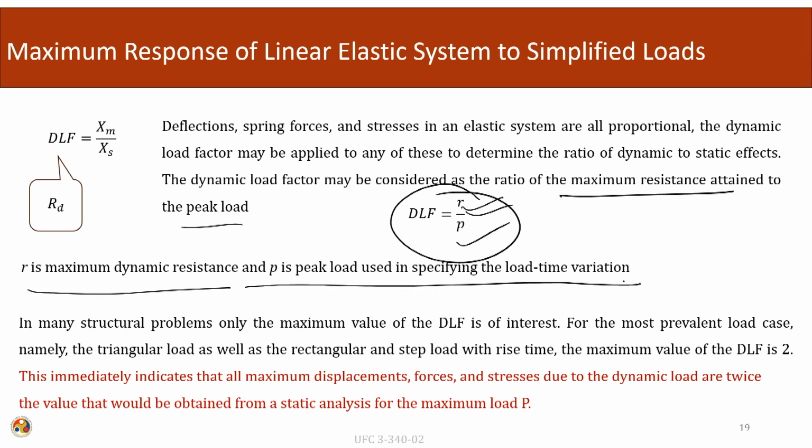In many structural problems only the maximum value of DLF is of interest. Normally the maximum value of the amplification is of interest. For the most prevalent load cases, the triangular load as well as the rectangular and step load with rise time, the maximum value of DLF is normally 2.